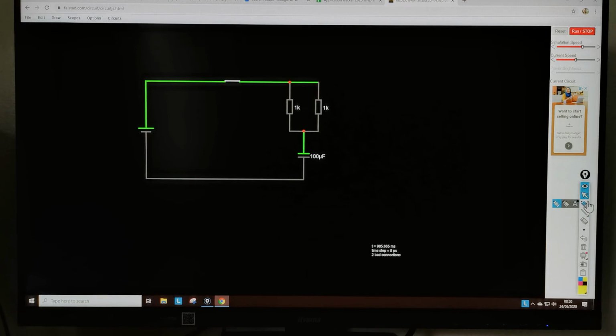But what you'll notice there is that we have a red dot there and a red dot there. The reason being that this is a warning sign that this is not a connection. Here, the top wire has simply moved across the top of this resistor without actually making a connection to it. So you can't drag across a node like this and expect it to be a connection. I'll show you how you need to do that. It's best to add in 2 separate wires.